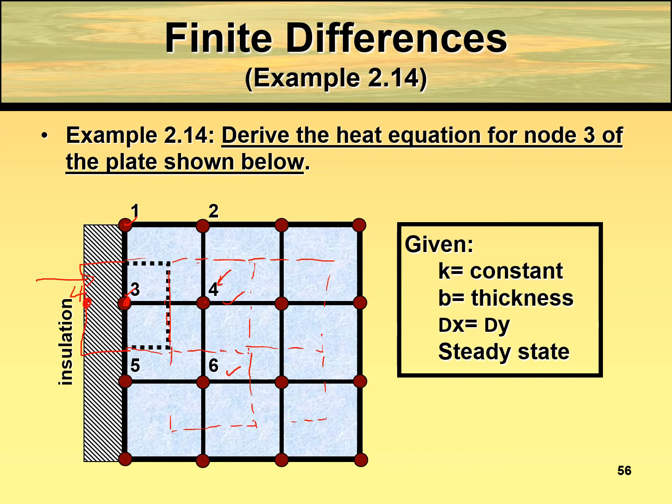So this is also 4, and now you get a full node. So for node 3, if you apply the equation, no heat generation, T1 plus T4 plus T5 plus T4 again minus 4T3 equals 0. So then you can apply this equation directly. But only if you have half a node and insulation, then you can mirror it, use the mirroring technique to get the full node, right?